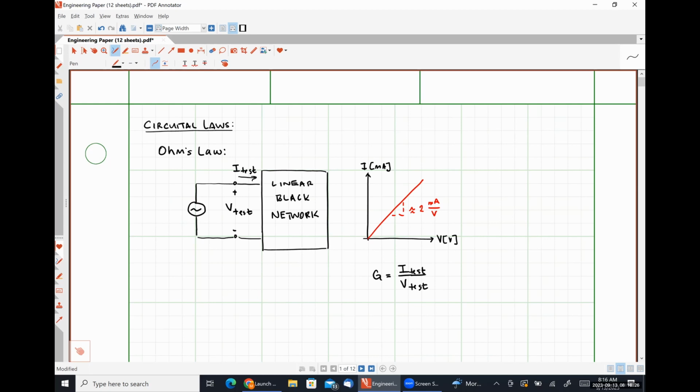the test voltage. Now, there were a lot of questions from you in previous years about what's supposed to be the independent variable and what's supposed to be the dependent variable in your graphs. If we were to plot things with voltage on the vertical axis and current on the horizontal axis, we'd still get a straight line, and the slope of this particular line should have been about 0.51 volts per milliamp.